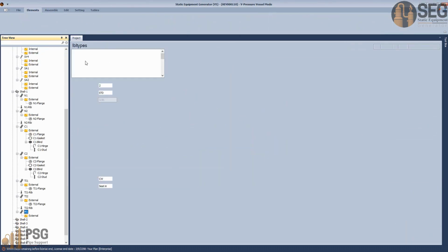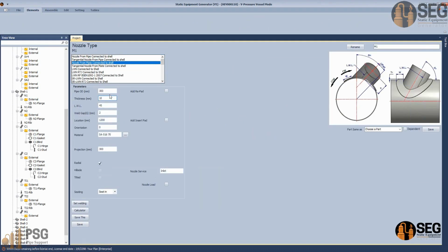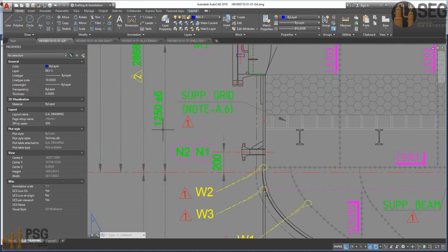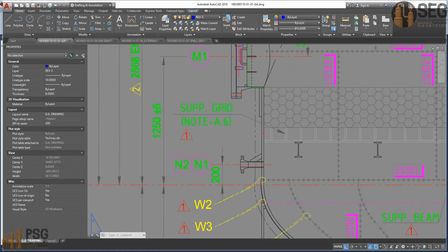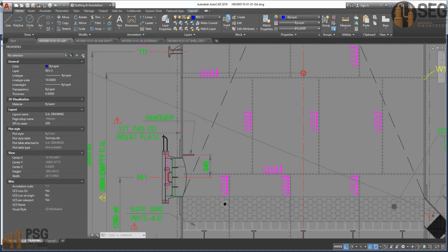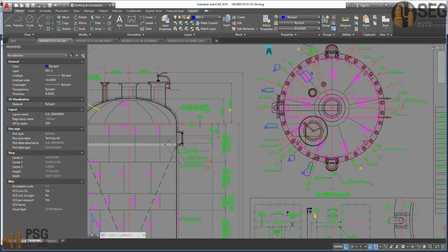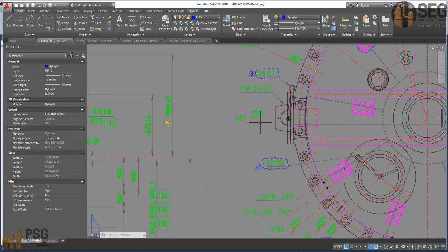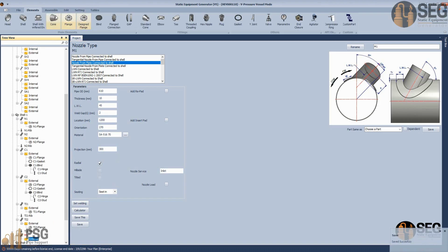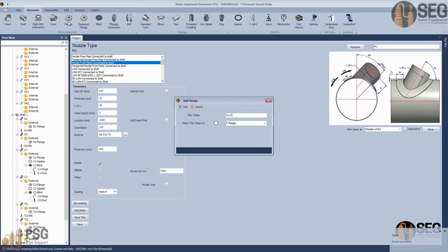And from here, select nozzle from plate and define the outside diameter and the thickness, the longitudinal welding line orientation, and here's the location of the nozzle. It's 1250, so we will decrease, so it will be that value. I need to edit it. And finally, the orientation of the manhole, so it's 270, so it will be like that. And let's add a flange.